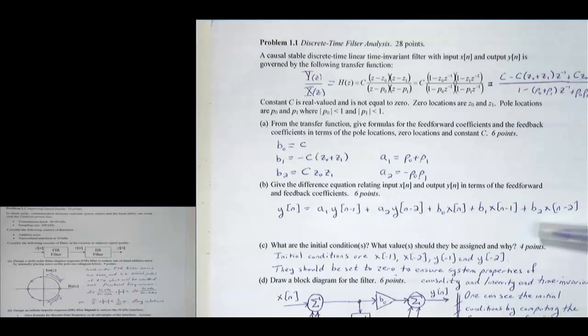I want to keep the zeros away from the pass band, because we want to allow some transition between pass band and stop band. And they should be conjugate symmetric or real valued zeros. I think some people drew zeros in there that were not conjugate symmetric. They might have just, again, speed, pressure of the test. Go ahead.